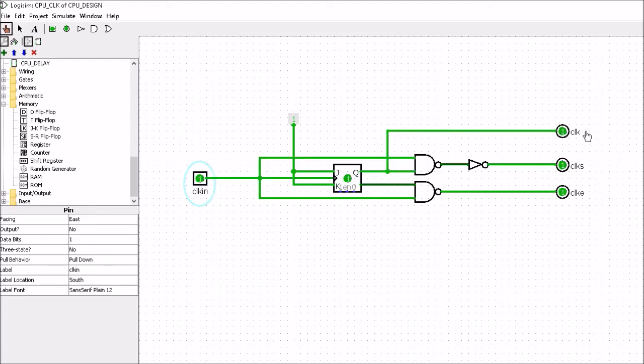So you can see here that this point here is running at half the clock rate of this point here, so it'll only change whenever that goes from a low to a high. So we take this here, and in effect this becomes our new clock. Our new clock runs at half the rate of this master clock.